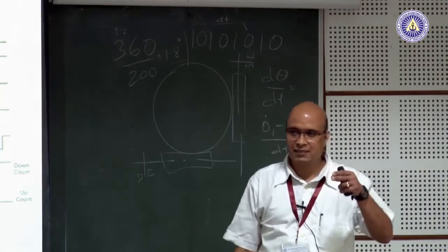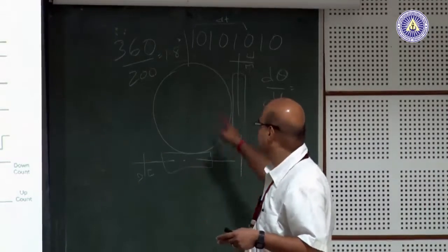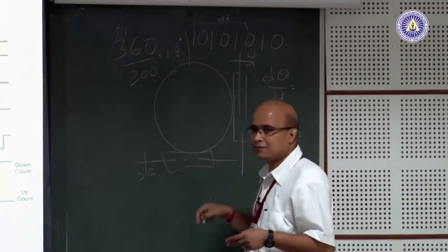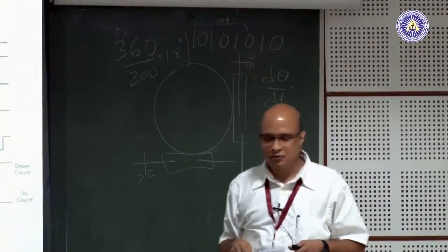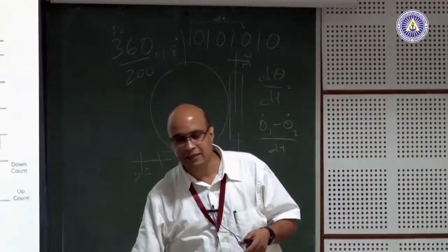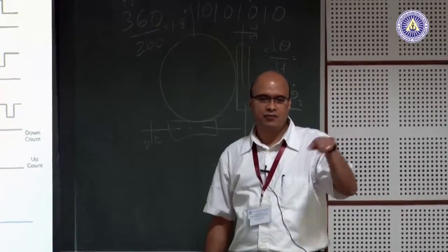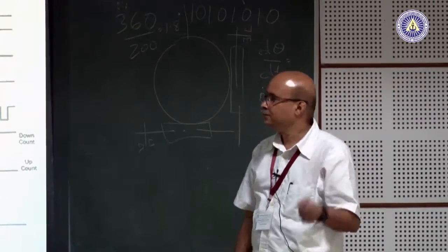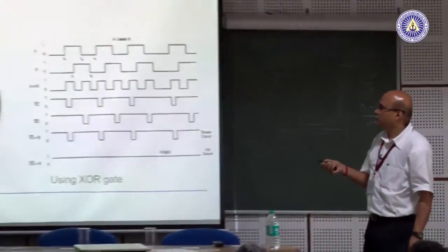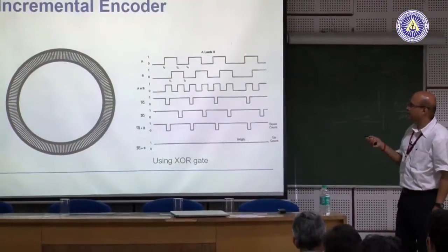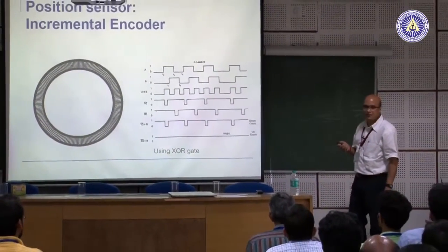That means, from one signal, very simple thing like an encoder signal, we can get the velocity, we can also get the acceleration. So, from an encoder we can get acceleration, we can get velocity and we can get position, and these three are required in our closed loop feedback control, for controlling the joint. And so, the basic signal that comes out is something like this, a high low kind of a signal. Now,